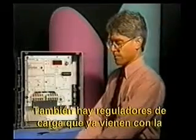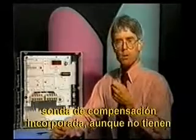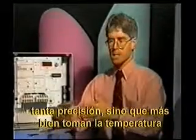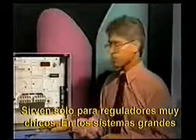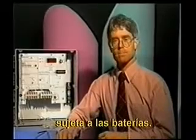You can also have charge regulators with the temperature compensation probe and electronics built in, although that's not quite as accurate. It's perhaps sensing the ambient temperature around the regulator. That would be appropriate for only very small regulators. For large systems, the probe should always be external and physically attached to the battery.